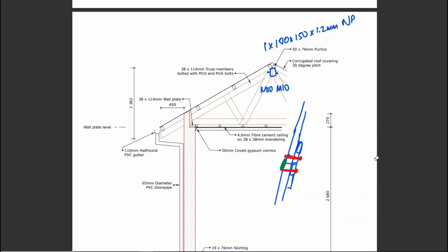Now the reason we do that is there's a whole story of dotted lines versus not dotted lines, where they meet flush versus sort of follow through. In this case, they follow straight through. You can see that this timber behind it has a dotted line. It indicates that it's going to the same endpoint, and you're going to need a bolt. The same is true here. That is a bolted connection.